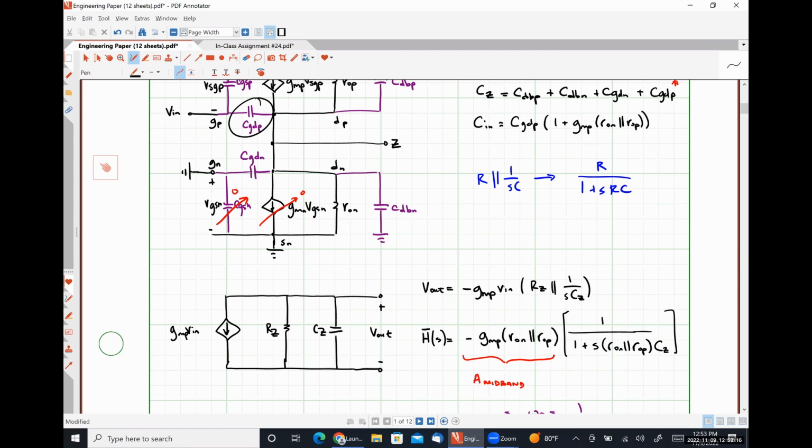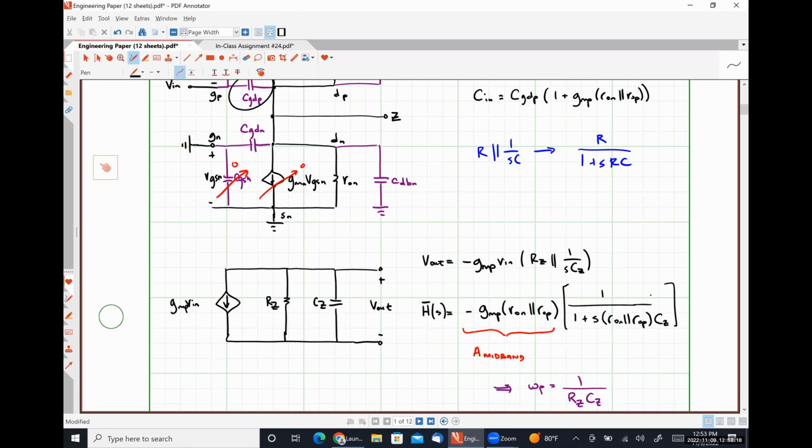All right. So now that we understand what's going on here, hopefully we all understand that our overall transfer function for this is just going to be our 2 transfer functions for each stage multiplied by each other, so that now we have a system with even larger gain in magnitude because we have the DC gain of the first stage multiplied by the DC gain of the second stage. And then we're also going to have a multi-pole frequency response because we have the frequency characteristics of the first stage being multiplied by the frequency characteristics of the second stage.